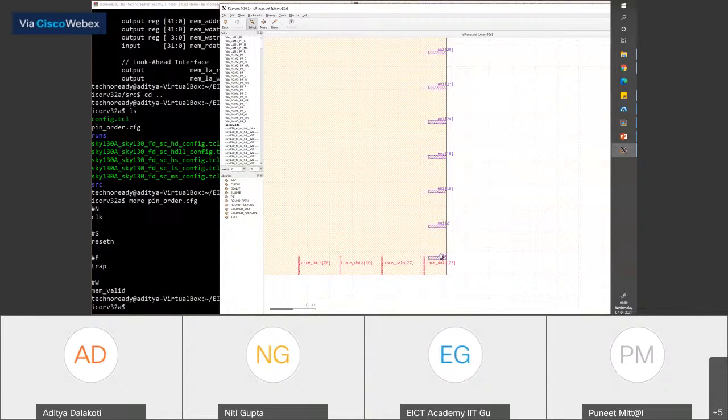Okay. So I will wait for everyone to catch up and be able to do this. After run synthesis, you need to do init floorplan. I'll type that. And then after init floorplan, you need to do place IO all. And then this file should exist in your temp directory. I'll wait for everyone to catch up and be able to observe this file. So I'll give you 5-10 minutes to do this. Please take it slow and get this done.